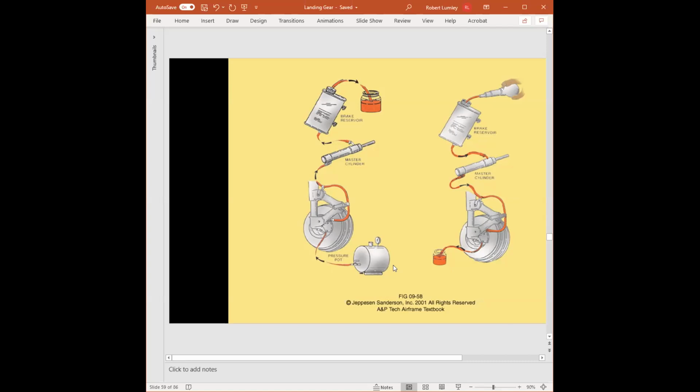And then the person will say, okay, holding. The person inside is to hold pressure on the brake and not release it, just keep on putting pressure down. Now, the bleeder will then open the bleed valve, and with the person pushing on the brake pedal, fluid will be pushed out through the caliper and into our container. We will then close the bleed valve and tell the person, okay, pump the brakes up again. And we repeat this until the brakes feel solid and there is no more sponginess.